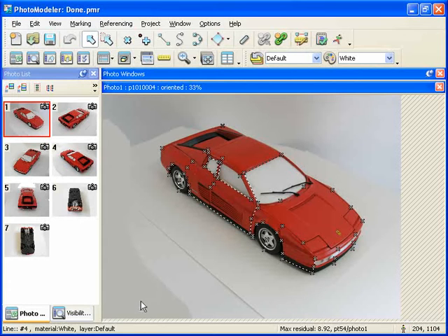The first shows information about the currently selected object. The second shows the largest residual in the project. Clicking here gives you the option of opening the photo and selecting the mark with the largest residual. The next icon shows a man, running if automatic processing is turned on, or standing still if it is not. Clicking here will toggle automatic processing on or off. The final section shows the XY position of the mouse when it is over a photograph. Or clicking on it will redisplay the last alert pop-up.